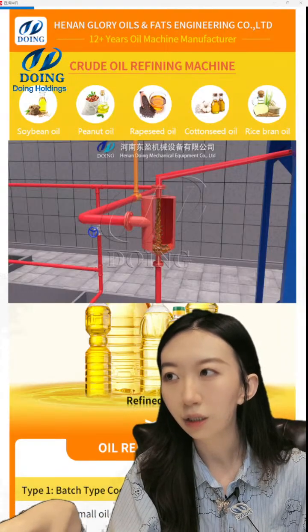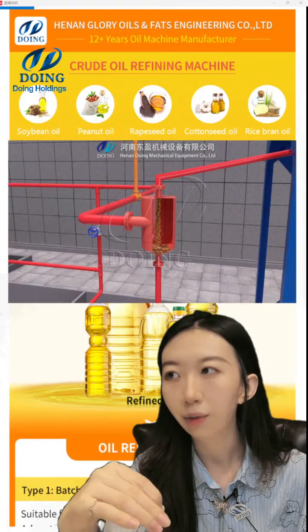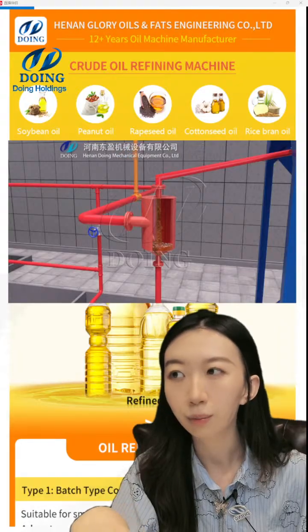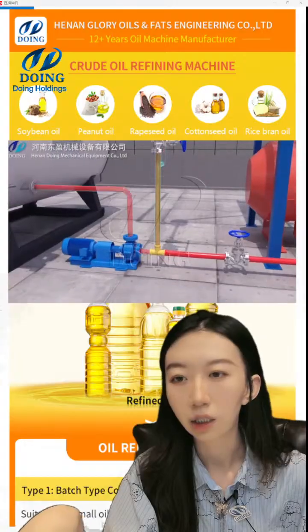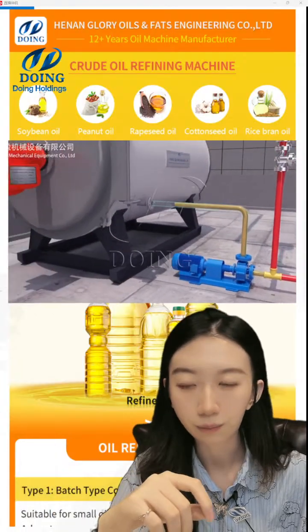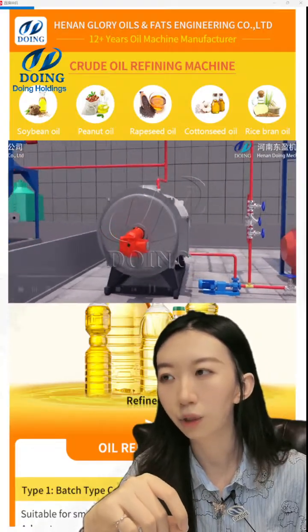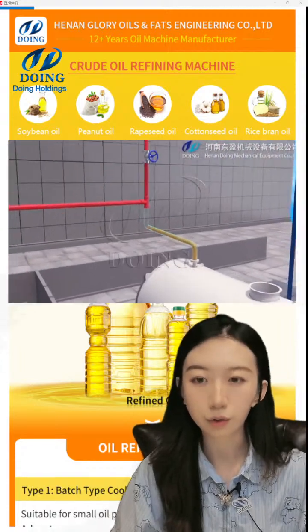This splitter removes air and water from the conduction oil. It can improve the heating effect of the conduction oil. And then the conduction oil flows down to the thermal oil furnace to be heated.